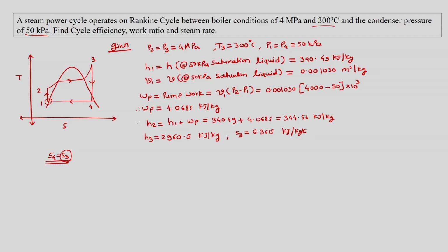So we will find out what is the saturated liquid entropy or saturated vapor entropy for the 50 kilopascal case. And now if our S3 is greater than that, then we would understand that the point 4 is in the superheated part.